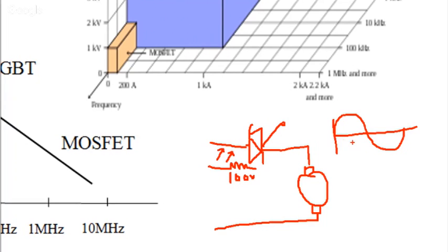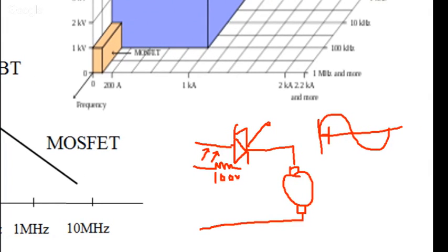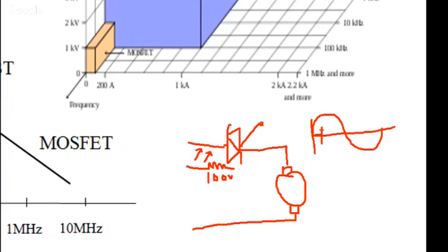So in case of Triac, what you can do is, during positive half cycle, at this point you're firing, so you get this portion. See, this portion, you get it for positive half cycle. Similarly, the negative half cycle, you can get this portion, the blue portion. It's not so clearly I drew, but still this positive, and here, so the portion in green which I am showing is clipped off. We are not taking it from the supply itself.